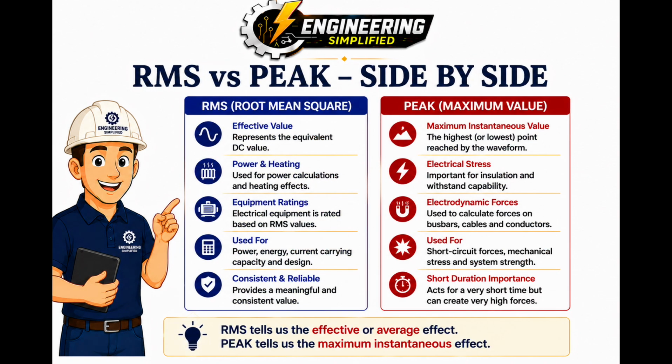When we compare RMS and peak side by side, their different purposes become much clearer. RMS represents the effective value and is commonly used for power calculations, heating effects, and equipment ratings. Peak represents the maximum instantaneous value of the waveform. Peak becomes important when we need to know the maximum electrical or mechanical stress that equipment may experience. So although RMS and peak describe the same waveform, they tell us two different things.